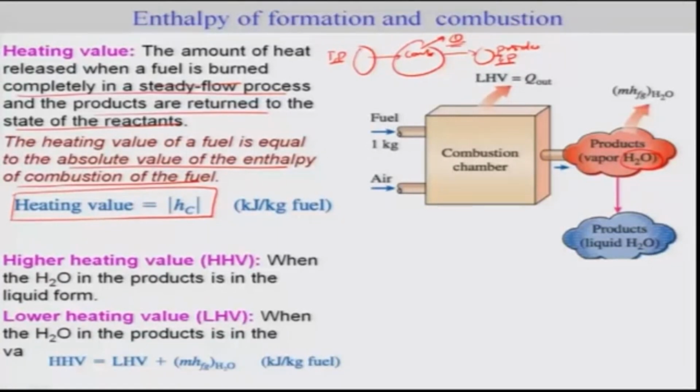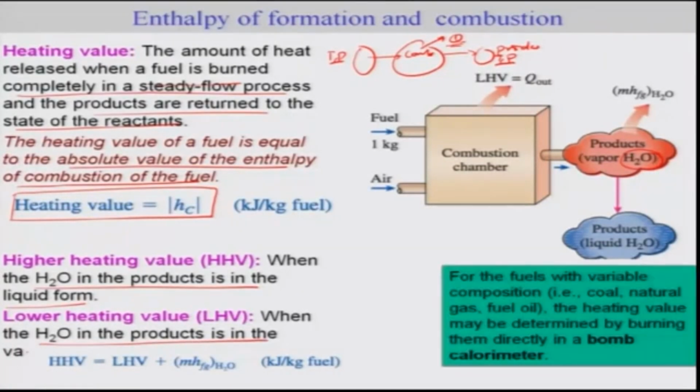Okay. So the higher heating value is when water in the product is in the liquid form, and the lower heating value is when water in the product is in the vapor form. Okay. So one can determine the heating value of the fuel by burning the fuel directly in something called bomb calorimetry.